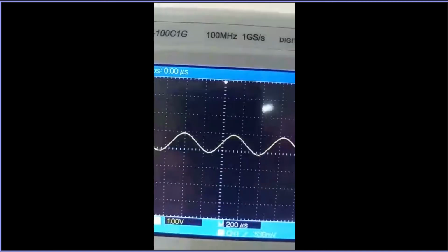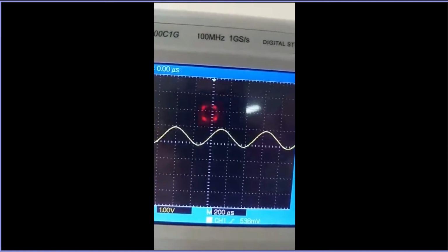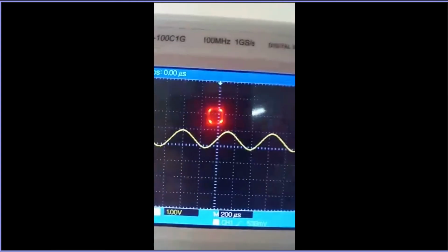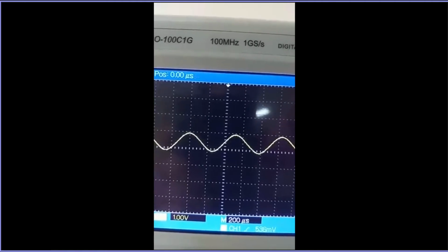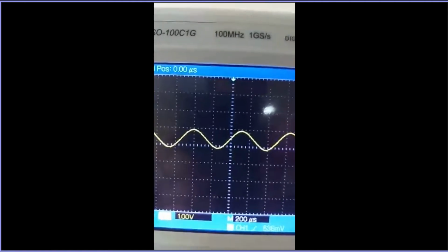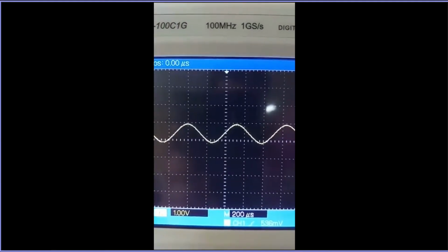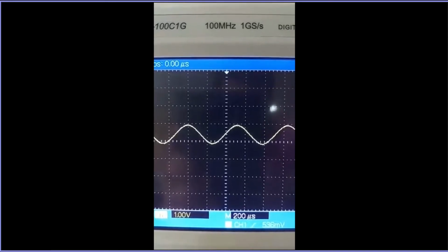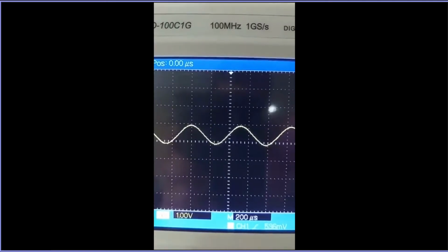And that's because one more layer of filtering we have applied, one more capacitive behavior we have added, right? So you can see the obvious, it was expected that we have a better output, right? The reconstructed signal. So this is the output of the fourth order low pass Butterworth filter. So for all the cases, we'll have this better output.